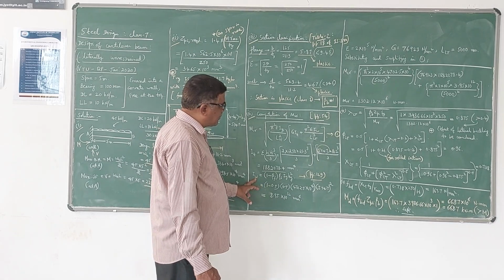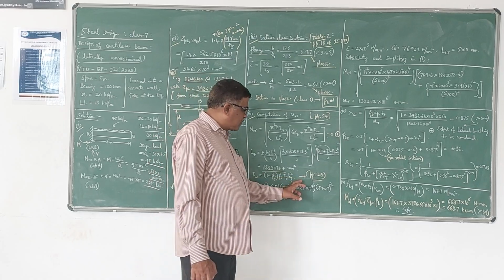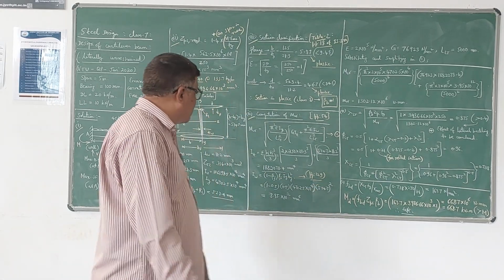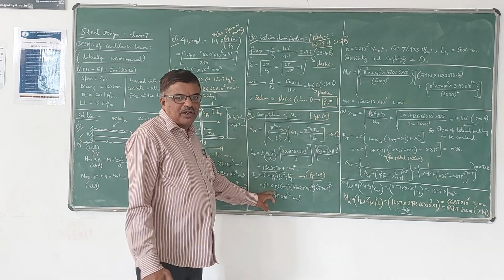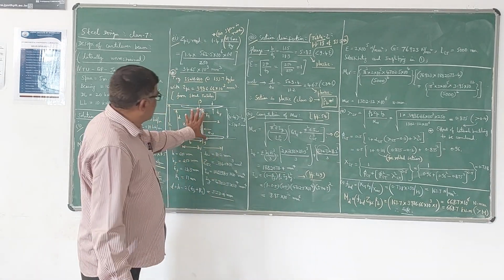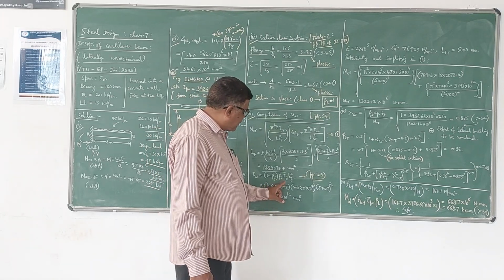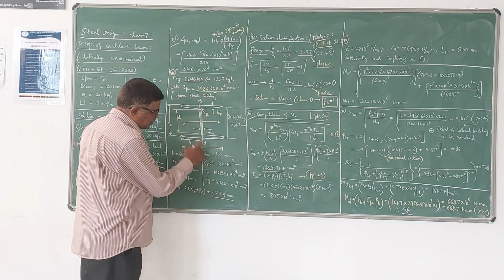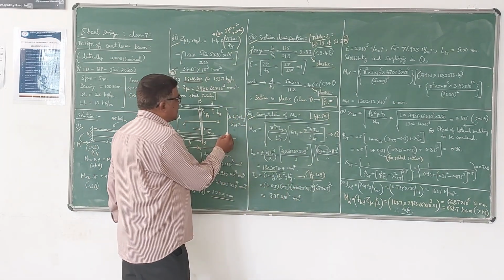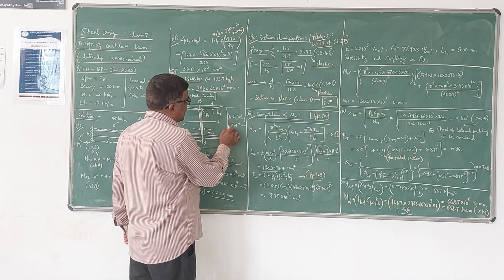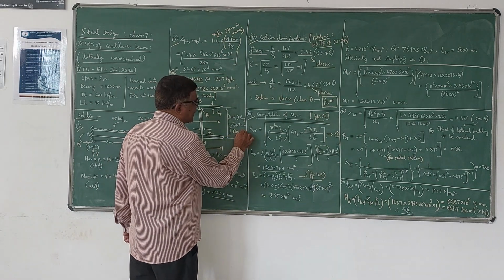Now this Iw is called the warping constant, which is given by a formula on page number 129. So (1 minus beta f) into beta f into Iy by hs square, where beta f is 0.5 for symmetrical sections. Here the I section we have chosen is symmetric, so beta f becomes 0.5 into 0.5 into Iy value for that assumed section, 4702.5 into 10 power 4, into hs squared, where hs is 600 minus 21.3.